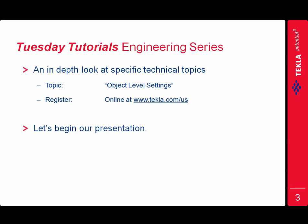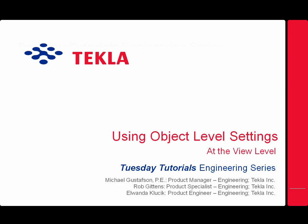Today's topic is object level settings, formerly known as drawing classifiers. Let's get down to business. We'll be using the object level settings at the view level. This is just the recommended flow from us at the engineering segment here in the Tekla office. Other disciplines might decide to use them at the drawing level.